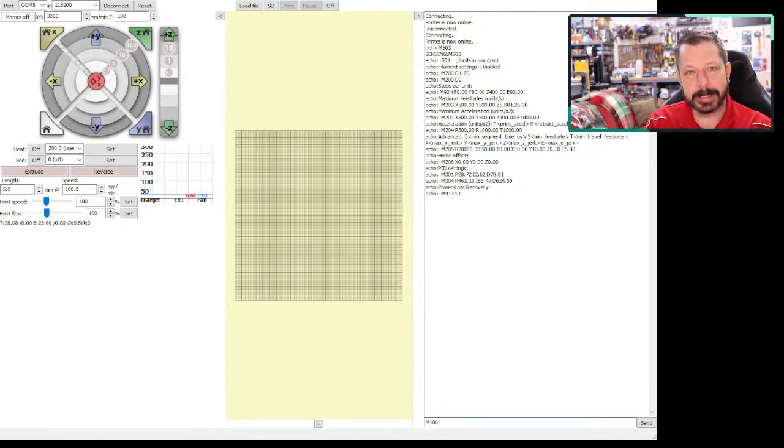And I need to tell it how much I want it to turn on. So I have values between 0 and 255. That range is based on the number of bits associated with turning the fan on. So 0 would be off, 255 would be 100% power, 125 would be about 50% power, and so forth. I'm on it full blast, so 255.